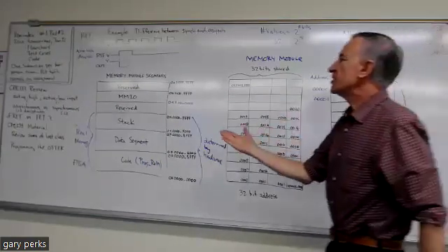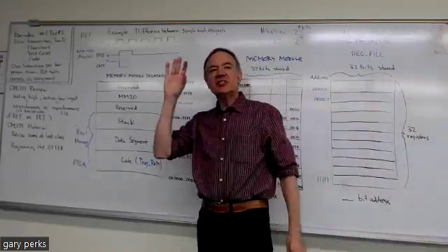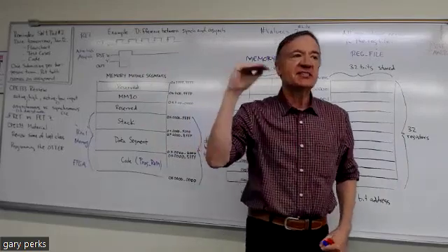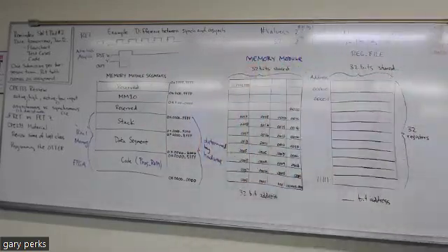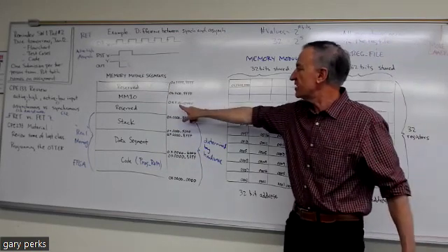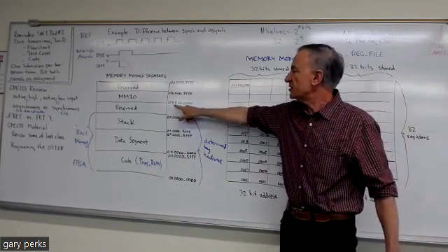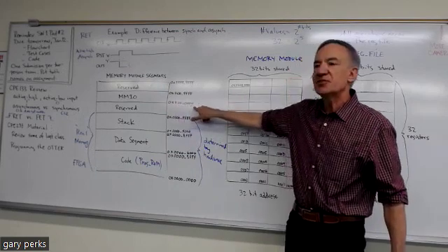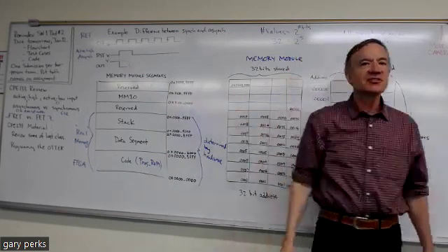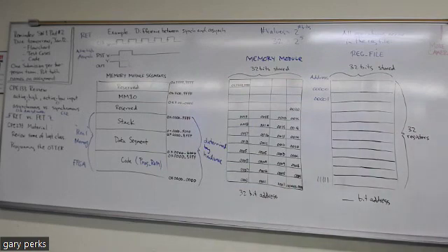So memory mapped IO is just that input and output devices have addresses. That's how the microprocessor distinguishes between input and output devices, by an address. The switches have this address, and then the LEDs have address 11000020, as you saw in that first assignment that we did in class.